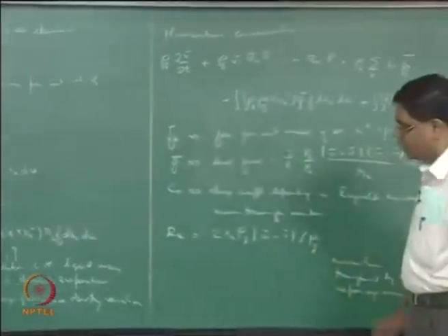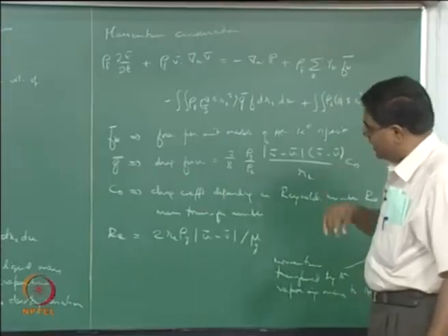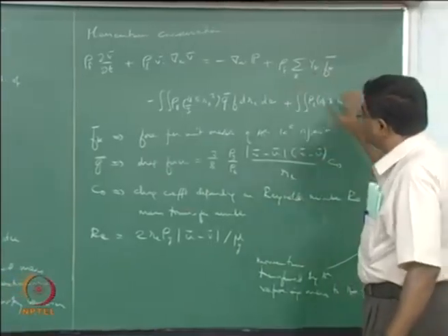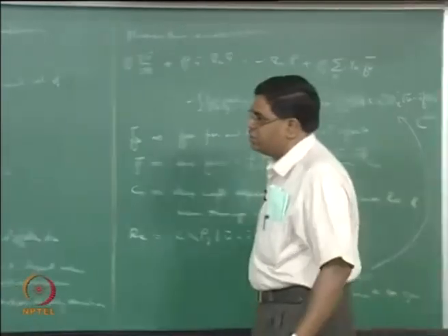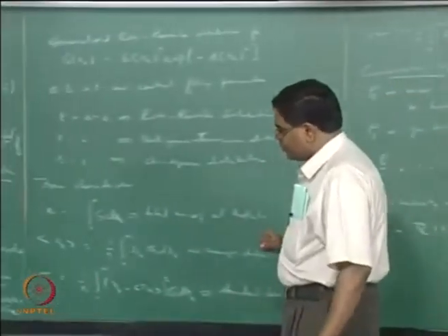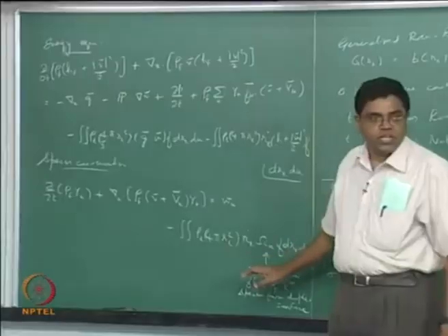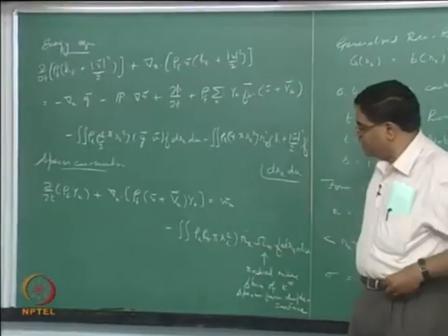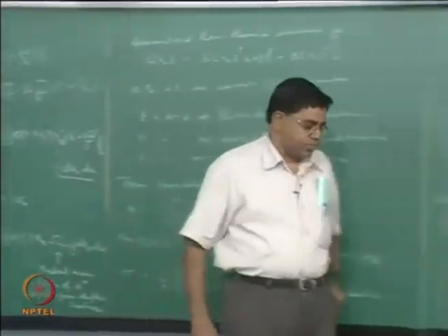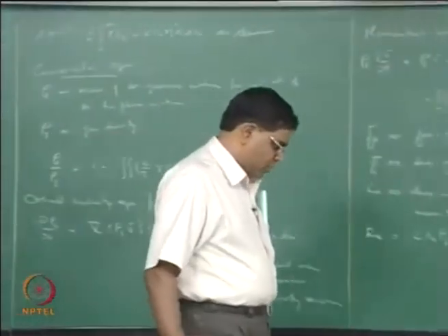That means the droplet would now add mass to the gases, it could now impart momentum in a couple of different ways, energy in a couple of different ways, and also throw in a particular species into the gas, and therefore comes in as source terms in the equations.